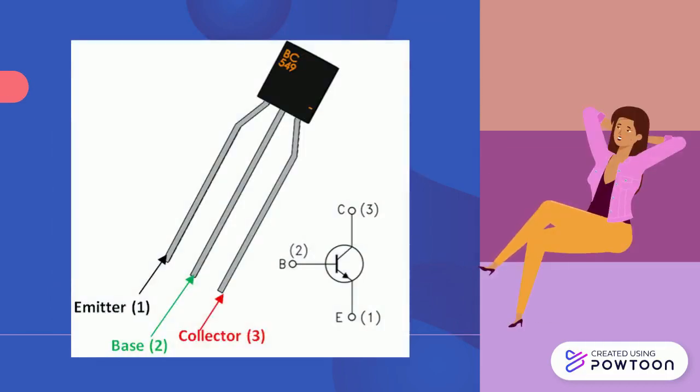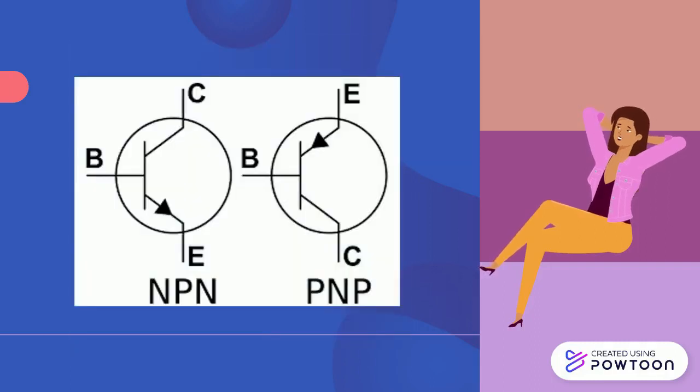In a circuit diagram, there are 2 different symbols for transistors. Both of these symbols have 3 connections, with a perpendicular black line on one wire to indicate the base, and an arrow on one of the other wires to indicate the emitter. In an NPN transistor, current is going out of the emitter, and in a PNP transistor, current is going into the emitter.